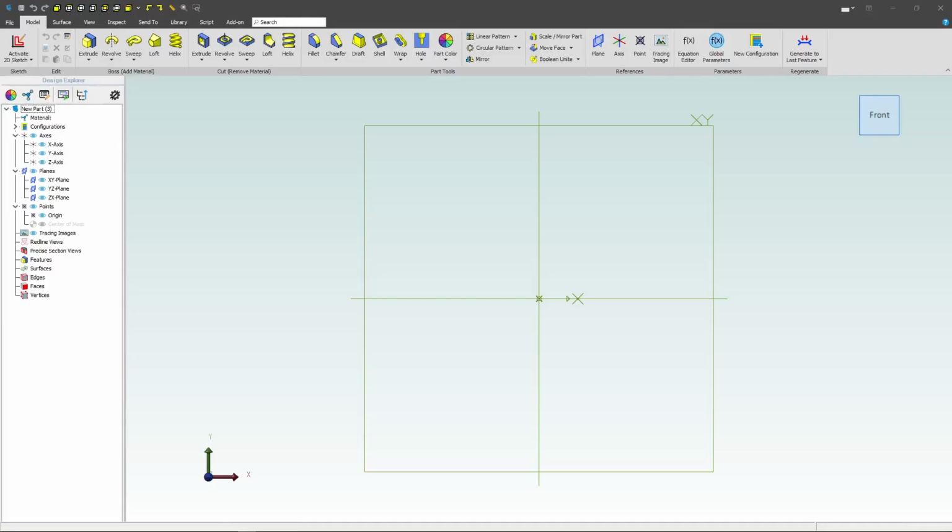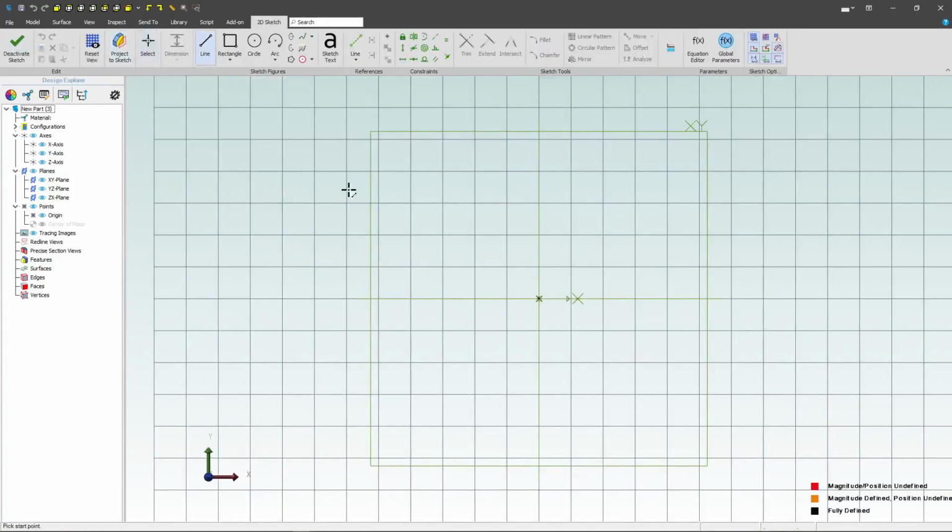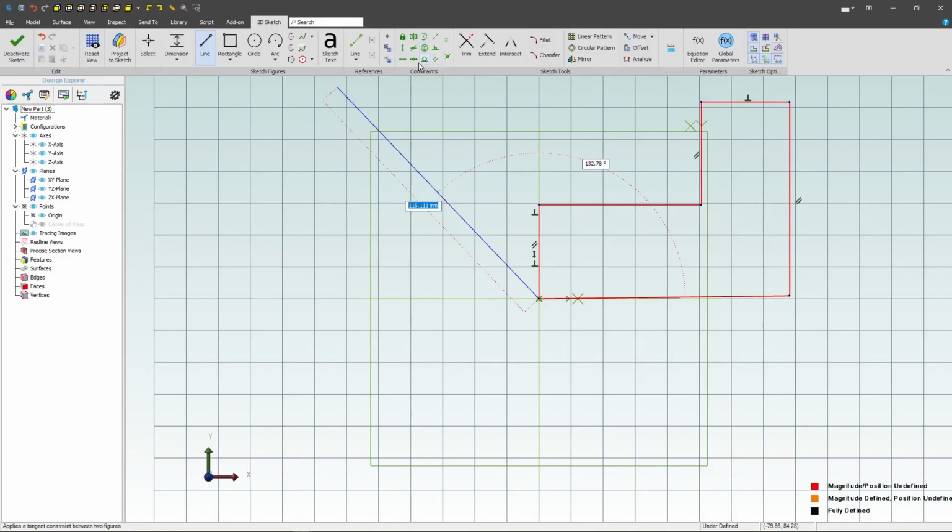Welcome to the second example of the Alibre practice parts. Let's start by sketching on the XY plane and activating a sketch. As before, I'll grab my line, click on my origin, and draw a vertical line. Again, we'll take note that blue constraints show up as we make our lines, and by adding the proper constraints, it makes easy work of fully constraining our sketches.